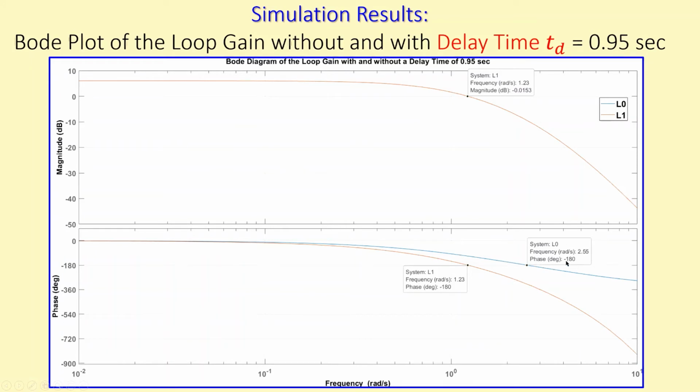What you can see is I just look purposely at the minus 180 degrees. And then if I go up, I can see that the orange line and the blue line actually coincide. So there's actually just one line visible, but you actually have two lines here. And if I go up, I can see that there's approximately here, maybe minus 8 dBs, but it is not 0 dB. So that means there is no stability problem. We are not at the edge.